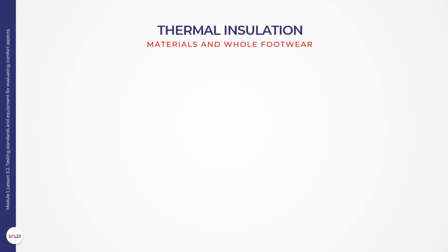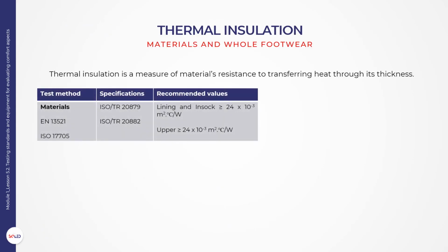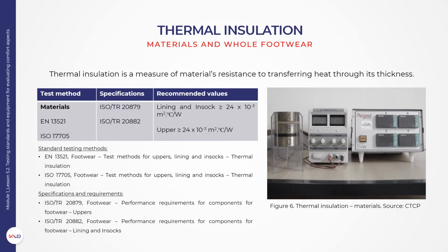Thermal insulation. This section includes 4 subsections describing the test and recommended values of thermal insulation of materials and whole footwear. The insulation of footwear against cold and heat. Materials. Thermal insulation is a measure of a material's resistance to transferring heat through its thickness. The thermal insulating power is expressed with thermal resistance that is directly proportional to the thickness and inversely proportional to the thermal conductivity of the material.